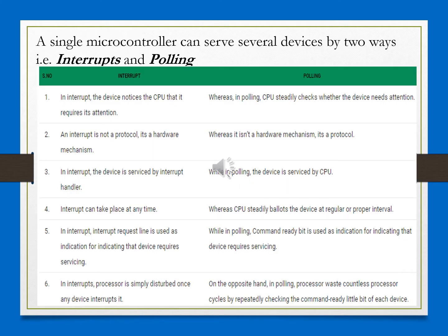In any computer, there are two ways followed in order to respond to interrupt signals. One method uses software instructions that jump to a subroutine based on the states of flags or the port pins. The second method responds to a hardware signal, that is nothing but the interrupt, that forces the program to call a subroutine. Here you can imagine it similar to the subroutines we had till now in our programs. In terms of interrupt, those subroutines are particularly called interrupt service subroutines.